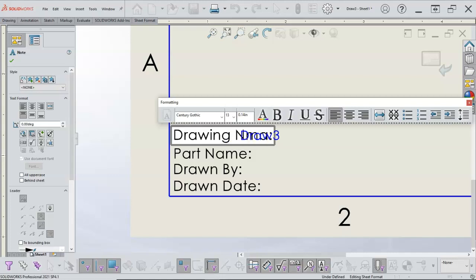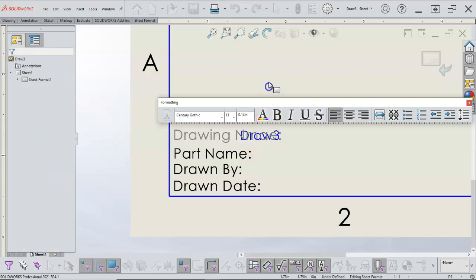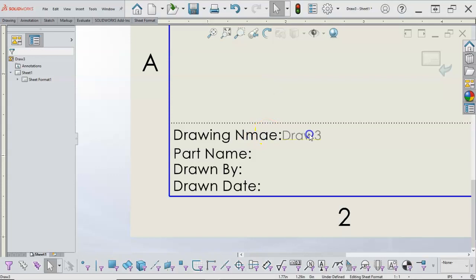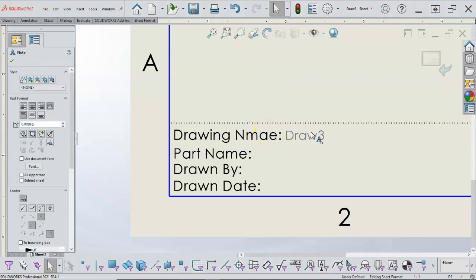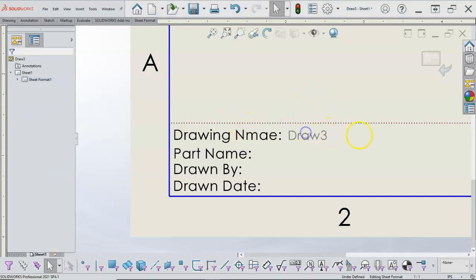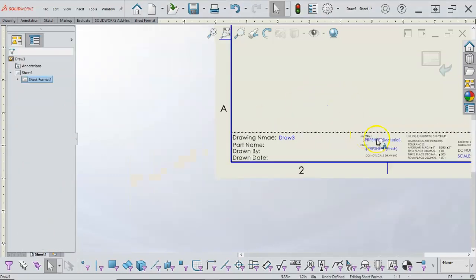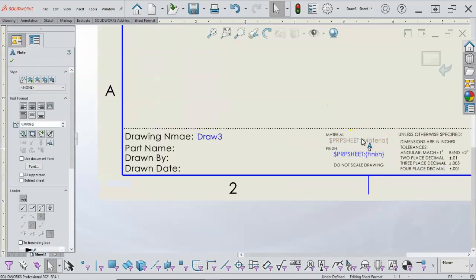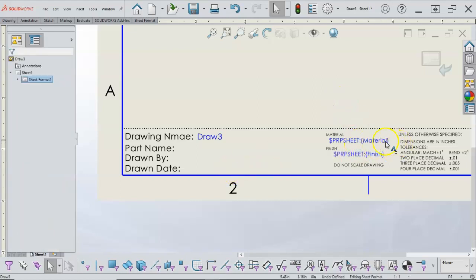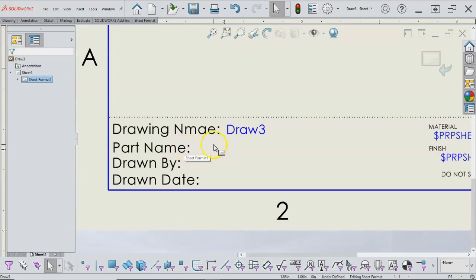This will overwrite the drawing a little bit, so we're going to have to go back in, select, and move that over. If I check the justification, it is currently at center justification, so we want to set that to left so it will grow in that direction. For that matter, I should check these as well. When it's center it could be okay, and the finish should be okay, if it needs to take up a little bit more room.